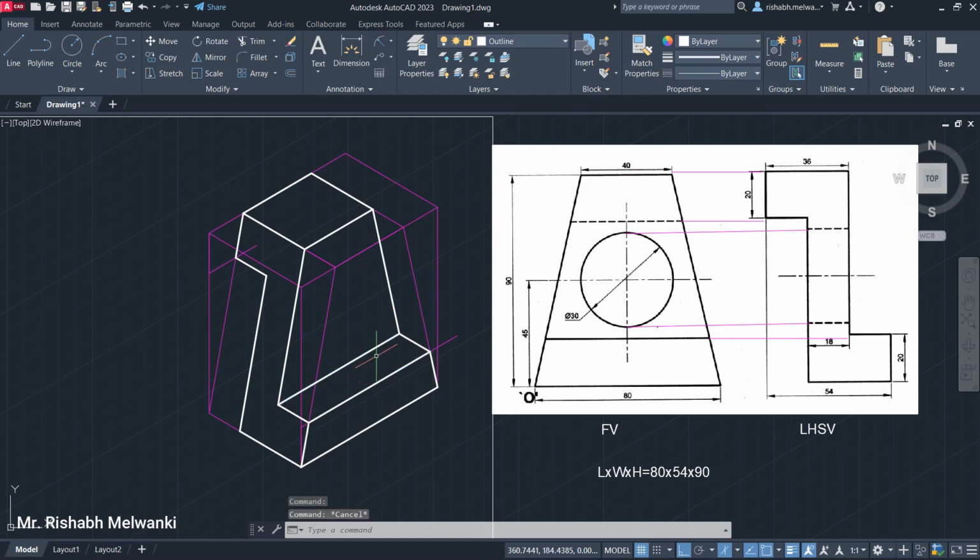So basically I'll draw a projection line, so change the layer, join midpoint of this line with the midpoint of bottom line, escape. Now the circle is at a height of vertical height of 45 millimeter, not the inclined height. So we need to move in vertical direction.